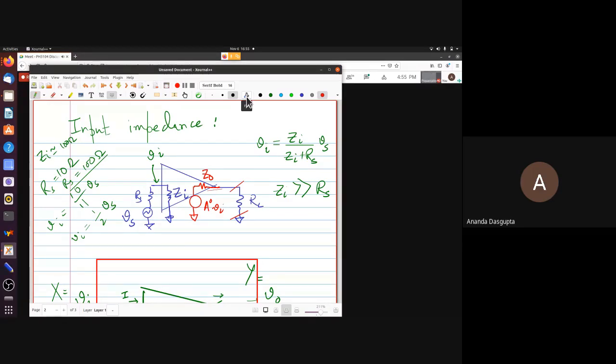So you could equally well use a small speaker or a large speaker and you would expect your circuit to still work. Of course, a large speaker usually takes a lot more current to work, so that may not always be great because your circuit may not be able to deliver that much current. But as long as your circuit works, different speakers with different impedances could just as well work for the same circuit. Simply because if ZO is very tiny, it doesn't really matter how big RL is. The fraction that you get in the output is RL by RL plus ZO.